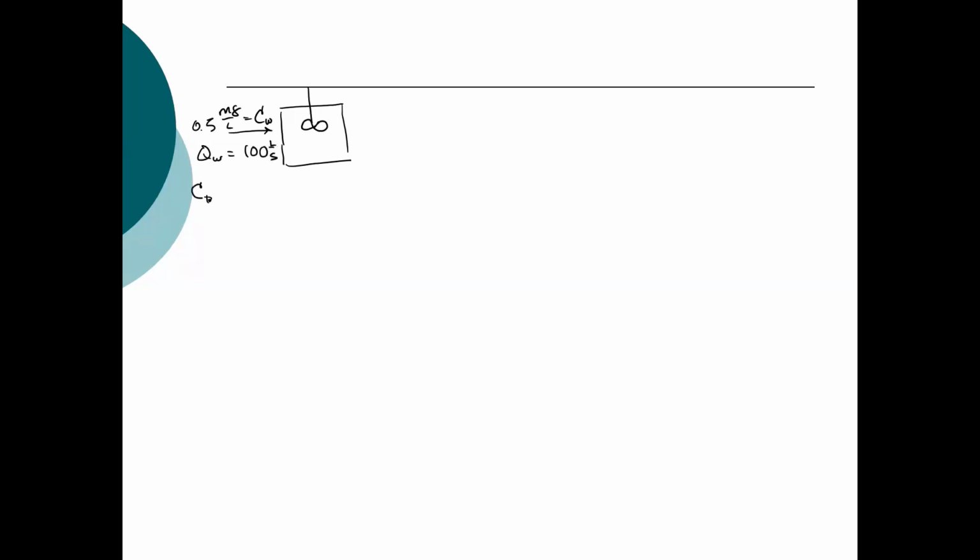Now the concentration of PAC in my waste is equal to what? 2.02? Not yet. Concentration of PAC in the waste stream. Oh, 0. Now we have a slurry, and the flow rate in my slurry is given as 1 liter per second. The concentration of PAC in my slurry is 2.02, and my concentration of benzene in the slurry is 0. So I can develop a mass balance for both my PAC and my benzene. We'll develop it first for the PAC.